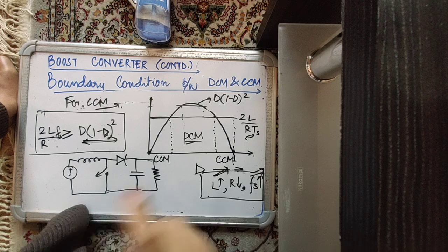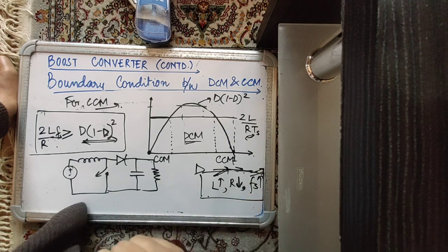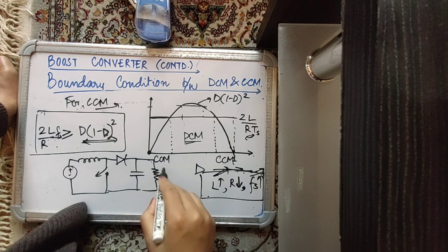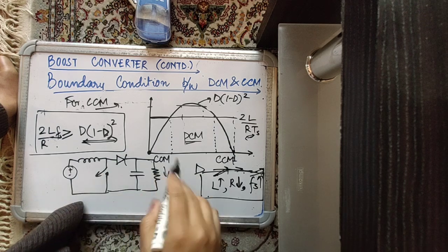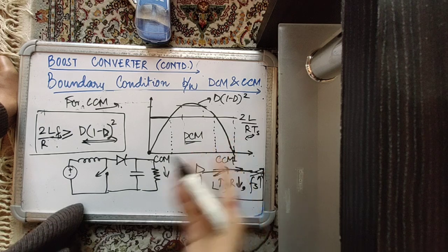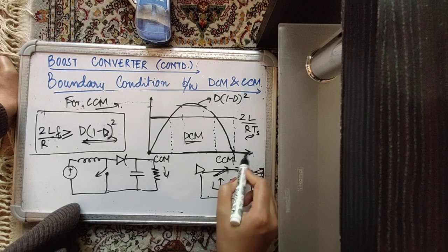Your switching frequency is very high. Similarly, if you have a very small value of resistance, it will make your time constant very high, your L by R ratio very high. So there will be a slow release of energy, a slow discharge of energy into the load, because of which your continuity of your inductor current will be maintained in the second half interval when it is supposed to release energy. अब बात आती है duty ratio की.